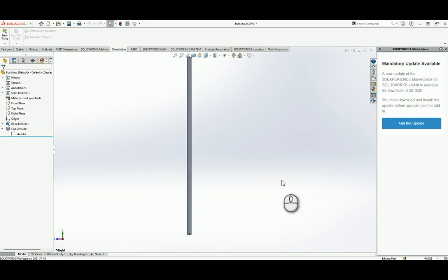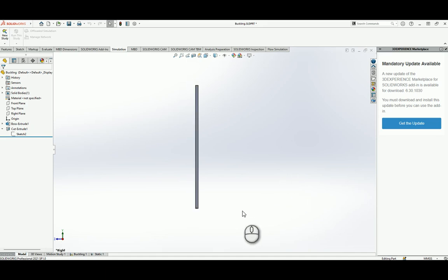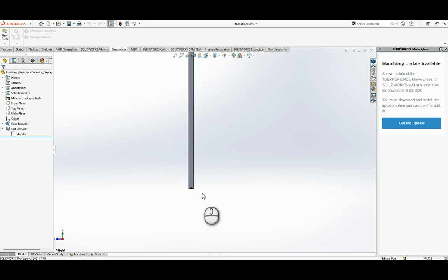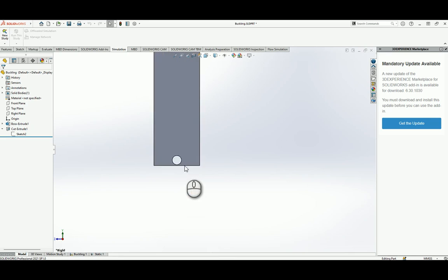So we're looking at example 2. Example 2 is pinned at the bottom, pinned on top, but of course the top is allowed to move in the vertical plane, well, vertical up and down, but the end is pinned. Right, so because we have this pin boundary condition, we need to actually physically make a hinge.